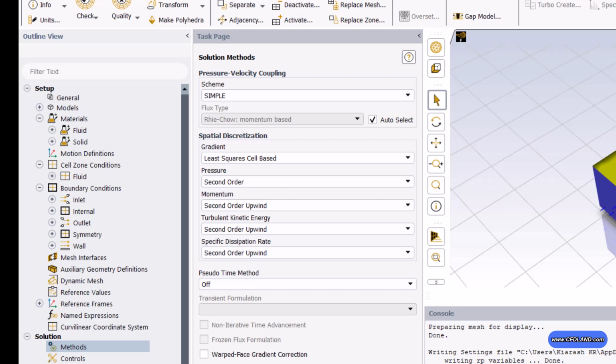So it will solve the momentum and continuity equations to handle pressure velocity coupling. And it works by guessing and then correcting pressure and velocity fields successively, and makes it efficient for many flow patterns and problems. So for this simulation, I'm gonna select it and use it.